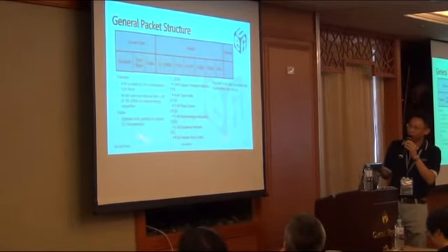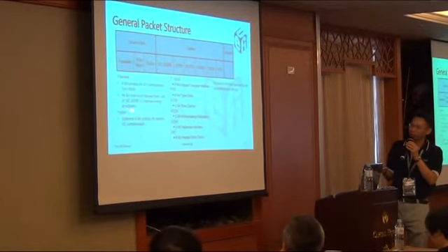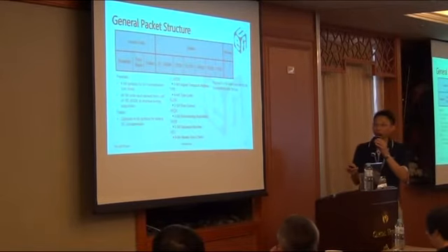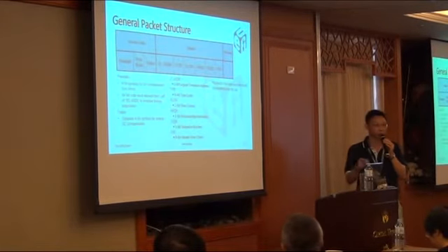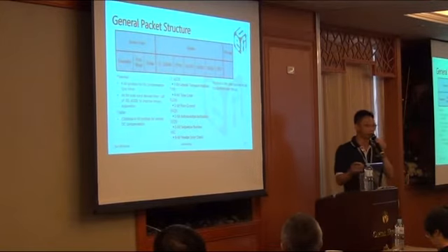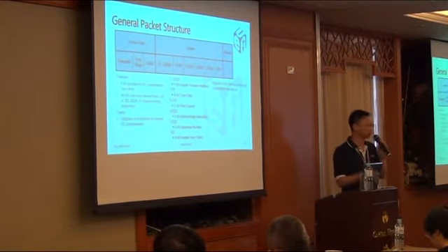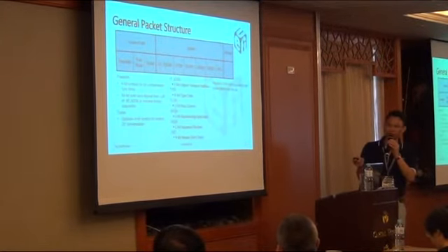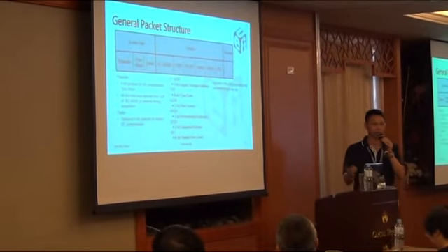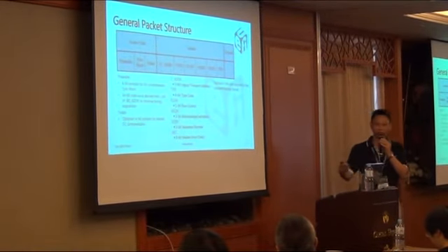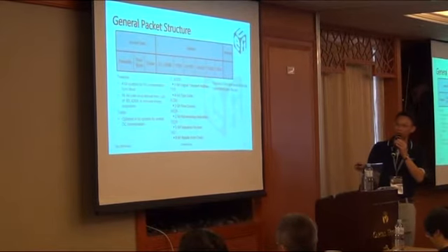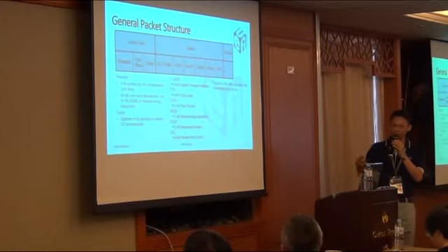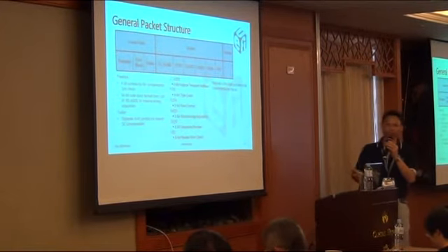Here, I'm not going to explain all the details, but there are important things like the Bluetooth device address. I especially want to highlight it, because the Bluetooth device address is just like a MAC address that a NIC interface requires. It's the same thing, and the way you assign the Bluetooth device address is the same way. So you can identify a Bluetooth device with it. It's unique. Even if two devices are the same model, the Bluetooth device address will be different.